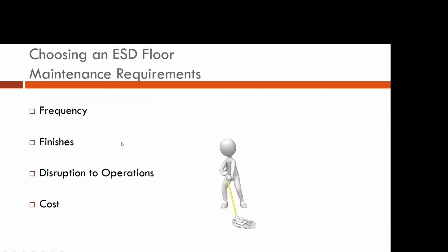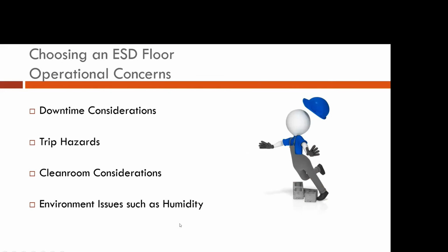Again, we always recommend going with an ESD floor cleaner. That way, no matter who's cleaning the floor, if they leave a residue on the floor, it will be an ESD residue. So it will help enhance the performance of the floor. Again, more operational considerations here.